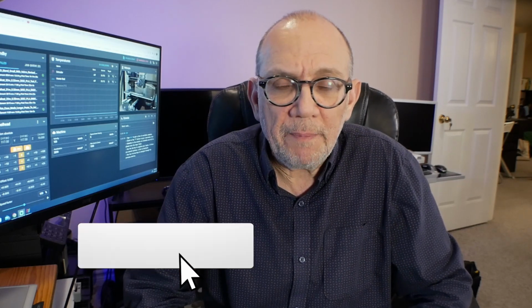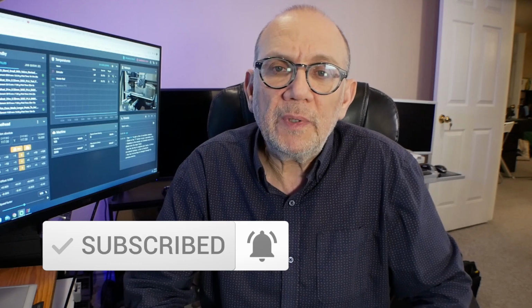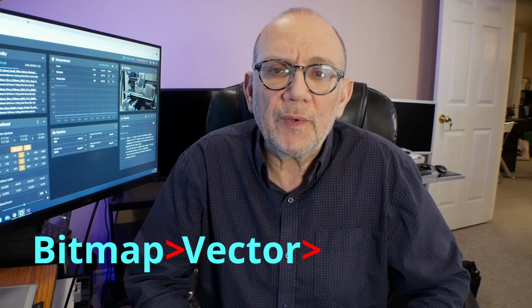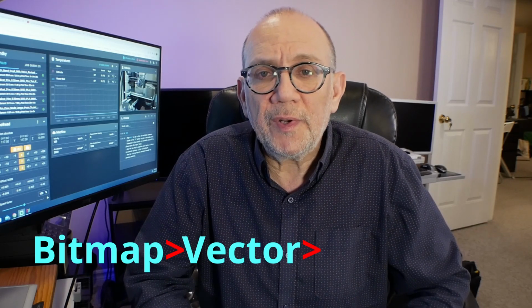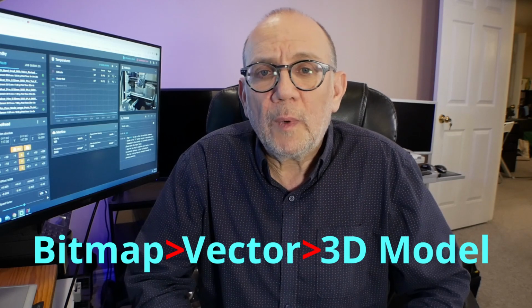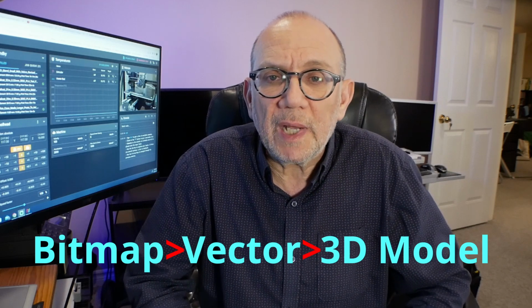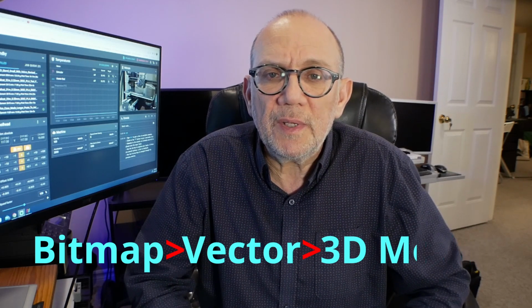So in order to make this work, you'll need a couple of free open source programs that you can download off the web. Specifically, you'll need Inkscape and FreeCAD. Now I'll put the links to these applications in the description below, and you can download them and install them on your computer. So the basic workflow for this technique is to take a bitmap image, convert it to a vector image, bring the vector image into FreeCAD, and convert it into a 3D model. What's really awesome about this, as you'll see, is that you can add your own personal touches to any images that you decide to use.